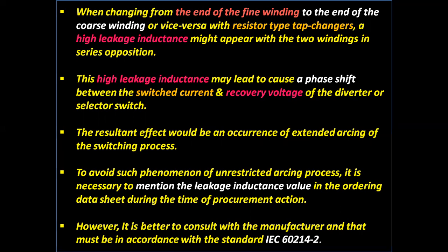To avoid such phenomenon of unrestricted arcing process, it is necessary to mention the leakage inductance value in the ordering dataset during the time of procurement action. However, it is better to consult with the manufacturer, and that must be in accordance with the standard IEC 60214-2.